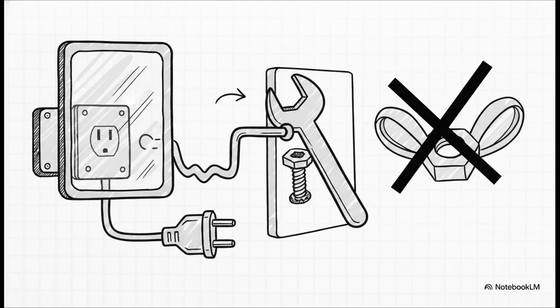We rely on die enclosures, fixed barriers, adjustable barriers, and awareness barriers. But I really want to draw your attention to interlocked barriers. These are absolutely critical because they are literally wired directly into the machine's control system. The second an interlocked guard is opened, it completely disables the actuating mechanism. It acts as an automatic fail-safe shutdown switch.